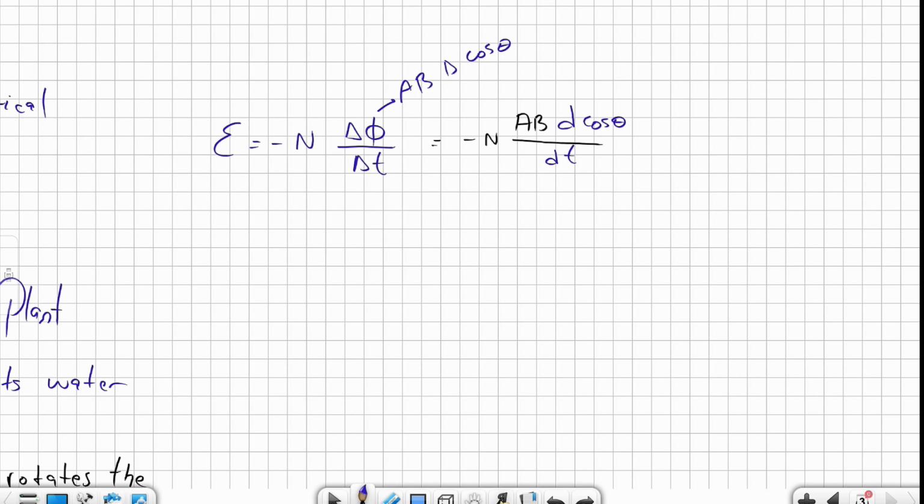To do that, we need to remember the equation that we talked about in chapter 1, which said omega is equal to delta theta over delta time. And when we generate electricity, we will keep the angular speed constant. Since angular speed omega is constant, every time will have its own theta, so we can get rid of the deltas. We can say that omega is equal to theta over time. When we rearrange this equation, theta will be equal to omega times time. So instead of theta, I will be writing omega times time.